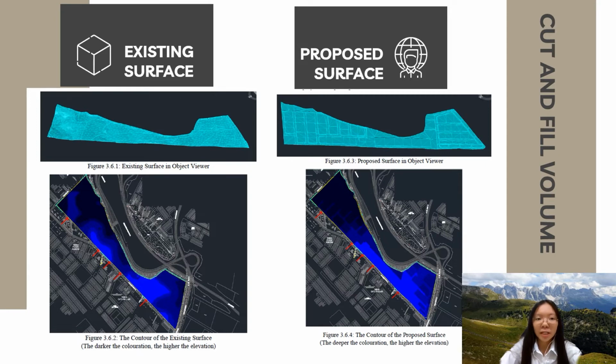We decided to use the software Civil 3D in computing the cut and fill due to several reasons. First, the manual calculation and computation process using either the manual grid method or cross-section method is quite tedious and prone to errors due to human mistakes. The results of the software calculation are also more accurate than those of manual calculation. Any correction or amendment can be easily done by simply adjusting the elevation for the proposed level as we require.